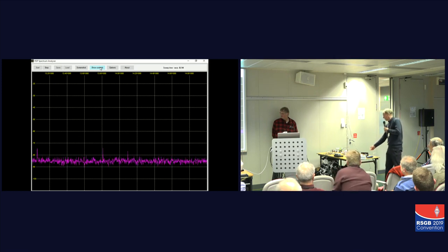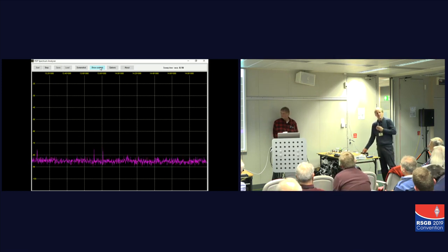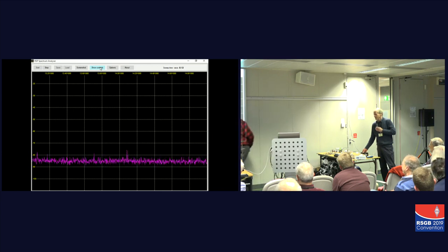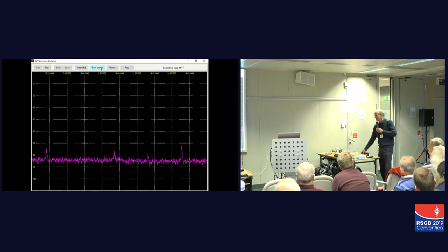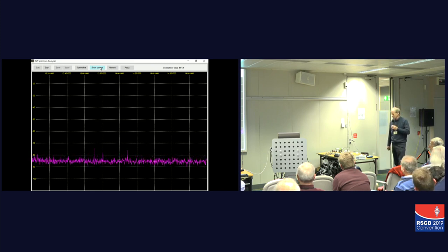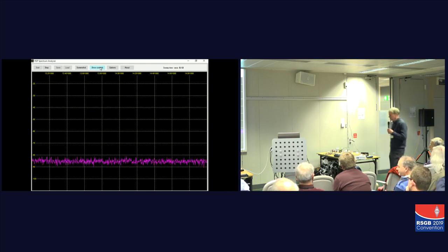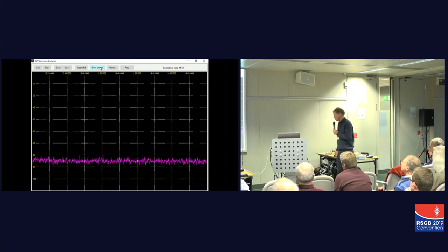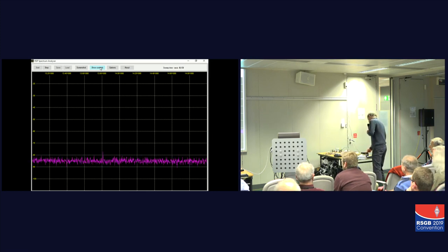You can find these in a media bed, which is available from well-known high street bed retailers who don't seem to have much knowledge of EMC, because, as you know, Class D amplifiers, unless they have good RF filtering on the speaker outputs, are going to cause interference, and this one certainly does, because the interference filtering is non-existent.